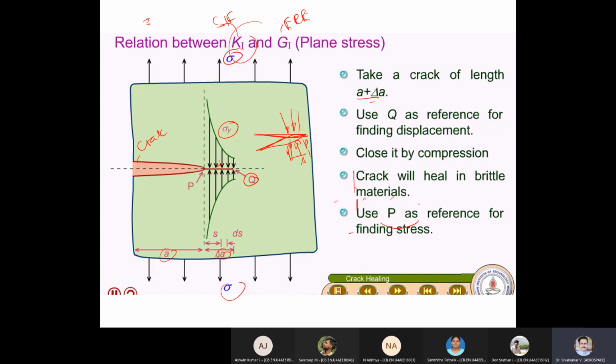It is an imagination. You have to imagine a crack has developed and it will become big, so I'm giving an additional force sigma y in this fashion. Why? Because I need more force on this side and less on that side. That is the reducing nature of this sigma y. This is the imaginary force I'm giving to close the expanding crack.